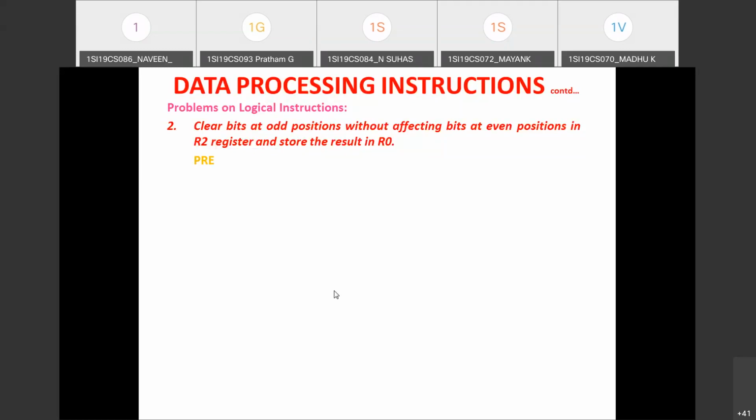It will invert the second operand and perform bitwise AND. Very good. So the mask value you are going to take should not be 5 here, as you do for the AND instruction, since bit clear first inverts the bits and then that data is taken for performing the AND operation.